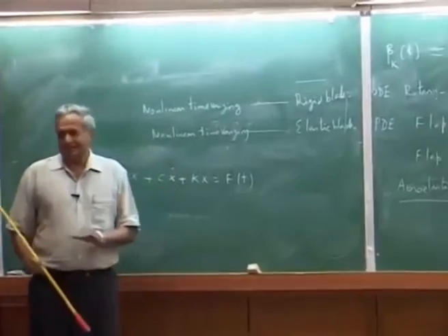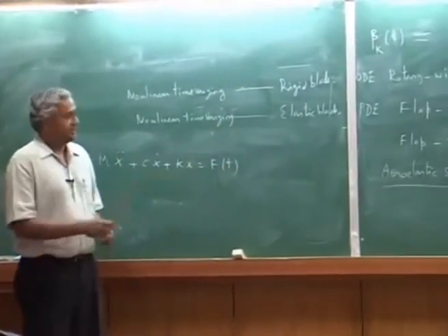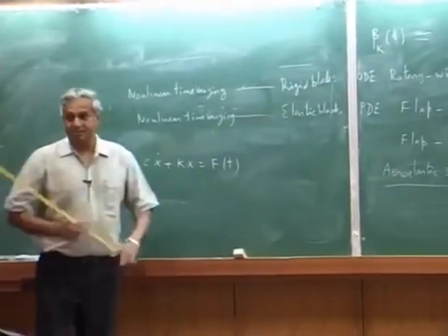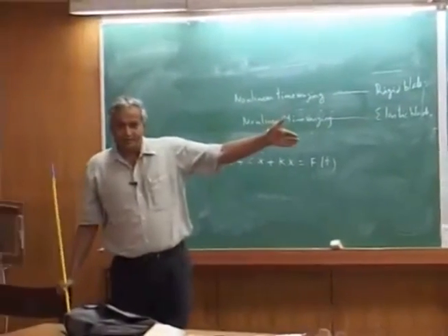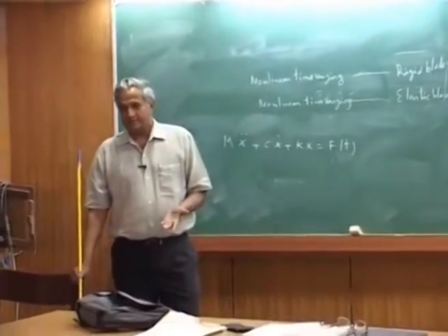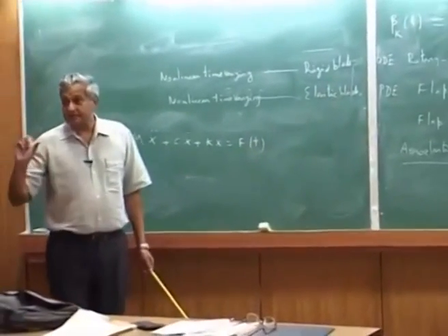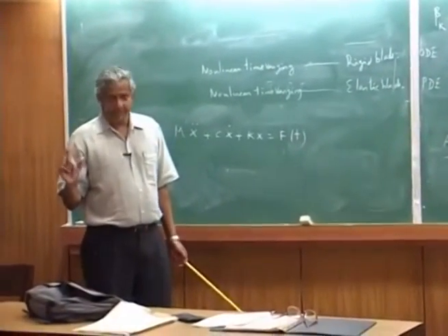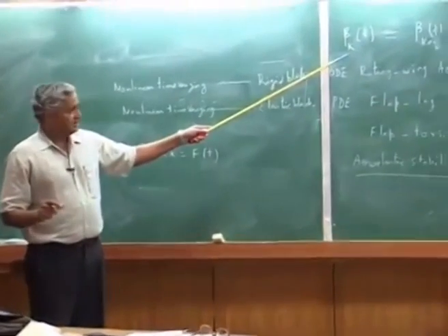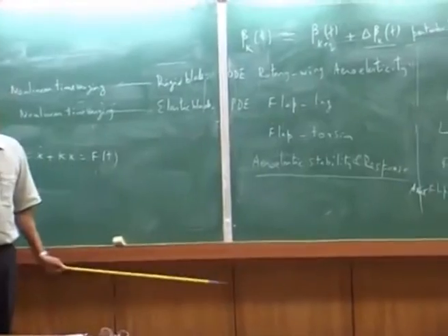On the other hand, you say, hey, I am starting directly with a rigid blade, that rigid blade I assume, then I will get directly the ODE equation. Straight away I go to ODE. Now, in the ODE, how do I solve? So the first thing is all the degrees of freedom. The degree of freedom is flap, degree of freedom is lag, if you are solving the flap-lag problem.